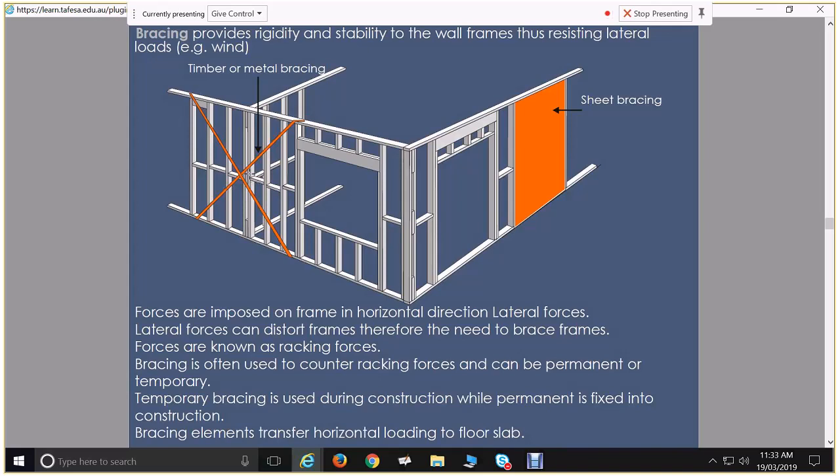Another limitation of this bracing is, to be effective, those bracing straps have to be at a certain angle. If we do a really short section of that bracing, then that bracing ends up being on this angle like this, and it's ineffective. Or if we do a really long section, the bracing ends up being at that sort of angle and becomes ineffective. So there are limitations to the length our bracing can be.